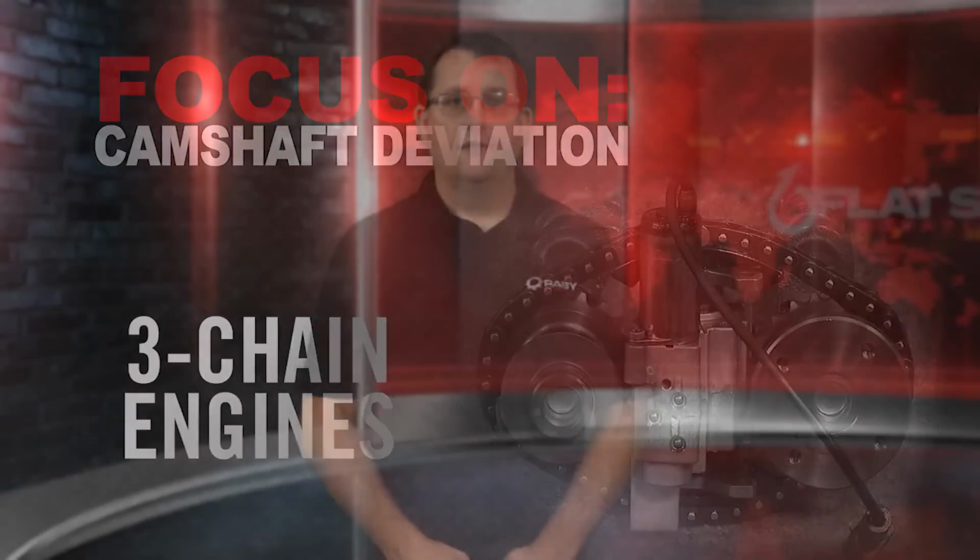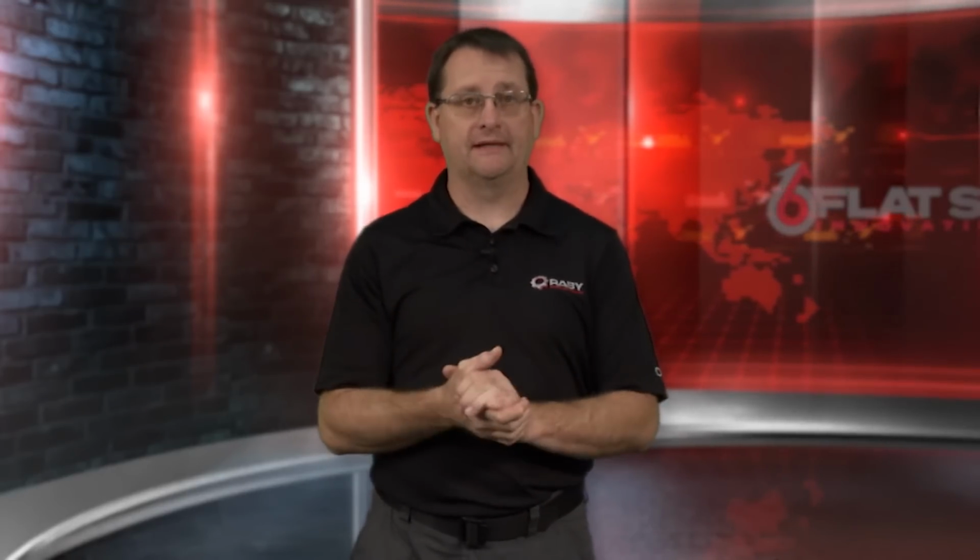So instead of going over the early 5-chain engines first, I'm going to go over the later 3-chain engines first, because those engines have a lot less things that will play into camshaft deviation values that are too great. Okay? We're going to go over what is a nominal value for this. We're going to go over what is my spec for a camshaft deviation, and we're going to go over what is out of spec a little bit later on.